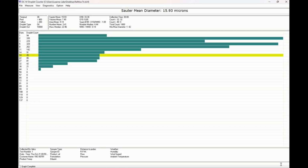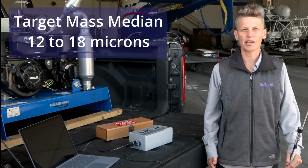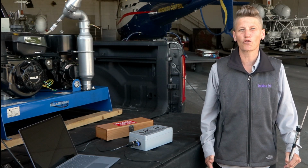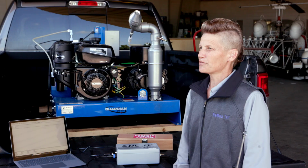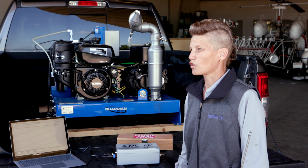Once the process is complete, the DC4 program displays the data collected in a simple bar graph, with the droplet size in microns on the left vertical axis and the number of droplets listed on the graph out to the right. For ReMoa Tri, we want to target a mass median of 12 to 18 microns. And when reviewing the overall data, we want to see that the majority of the droplets are in the 8 to 30 micron spectrum. If the droplet spectrum is not correct, adjust the equipment to adjust the droplet size.